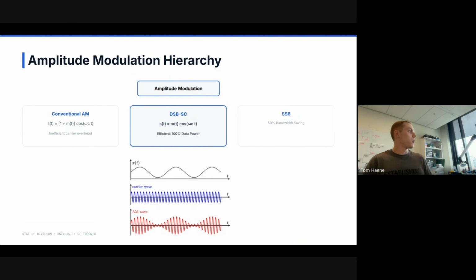Good question. So here, actually, you can think of it mathematically. How we do modulation is actually, in this case, a multiplication. It's that simple. You might be like, what? But if you actually did it, even on Desmos, if you made two cosines, you draw them individually, plot them, and then you plot the product, you multiply them, you'll get this. And that's actually how you encoded the information, the message, onto your carrier.